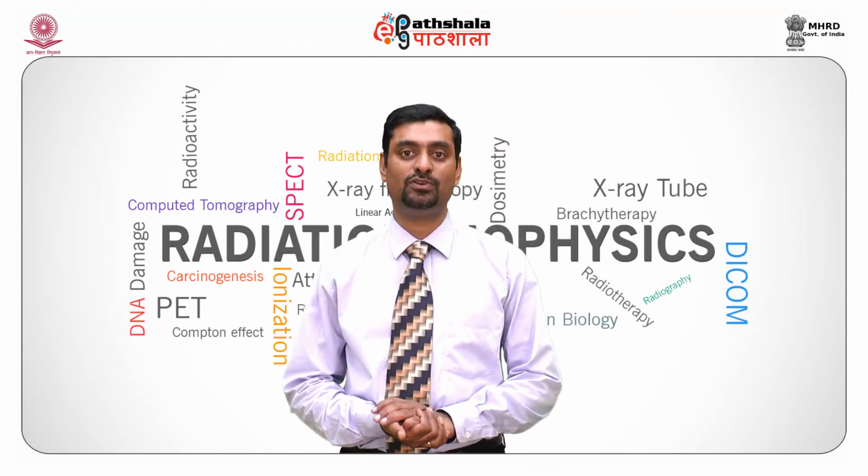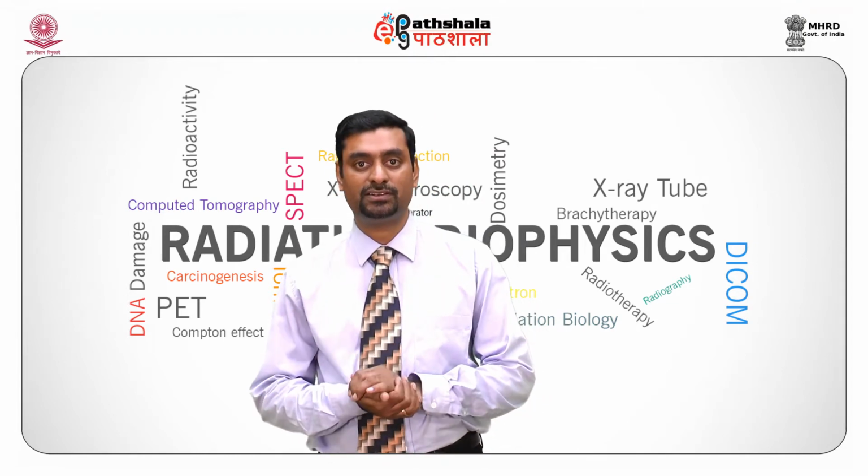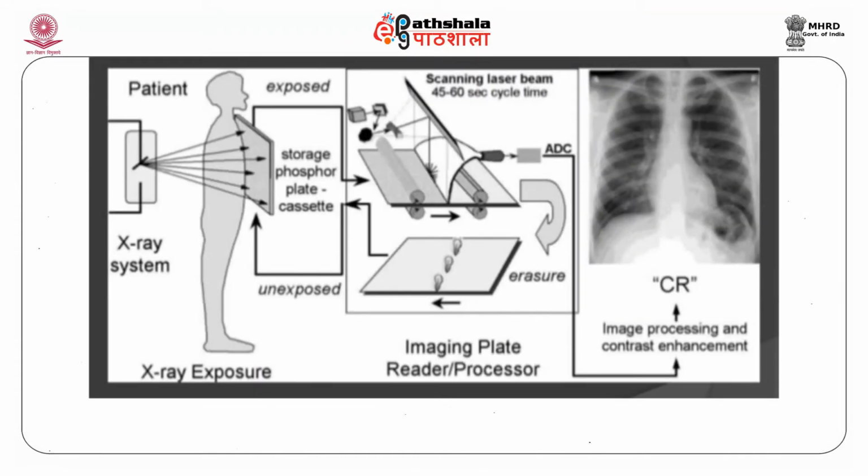Next, we move on to digital radiography systems. In a digital radiography system, there are flat panel detectors which have indirect conversion. In the indirect conversion, we have charge coupled device and amorphous silicon technology. In the direct conversion, we have amorphous selenium technology. Let's talk about indirect conversion technology, and we talk about charge coupled device, CCD.